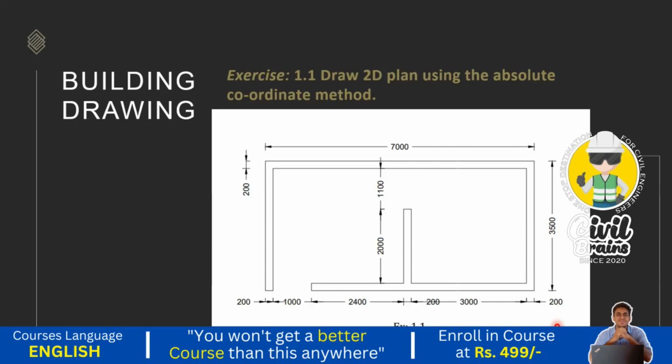So nowadays the load bearing structures are very few. In most cases it is outdated. No one is going to construct load bearing structures. For small structures, we are going with the load bearing structure, and it will be economical also, and for structures where the usage is very low, in those cases also we are going with the load bearing structure. Okay, and the construction method is also very easy in the load bearing structure, and the materials consumed are also very less, and it will be economical. So we are using those load bearing structures.